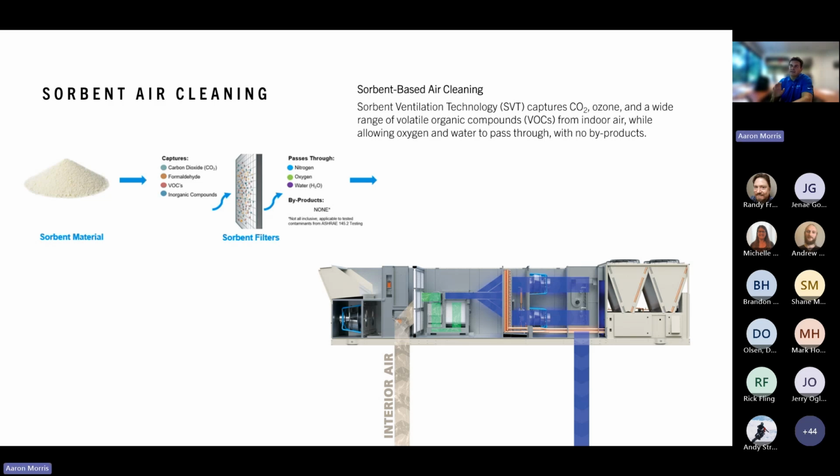And again, all these products I mentioned are tested to ASHRAE 145.2 so that we have quantified efficiency levels that can be plugged into the calculation tool to help determine if you're meeting the indoor air quality per ASHRAE standard 62.1.